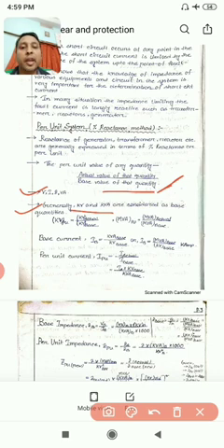So you will see the kVA per unit is kVA actual by kVA base. While you solve numericals, you will find it very clear. Just go through the formulas here, I will give you the idea. And here MVA per unit is MVA actual by MVA base. These two we have considered fixed, that is, V is fixed and VA is fixed, and according to this we will calculate the other values. First is I, then Z, we will calculate one by one.